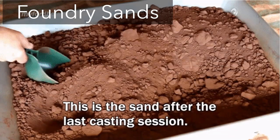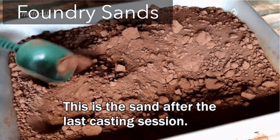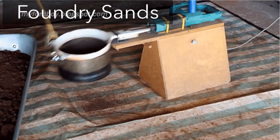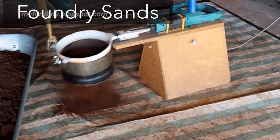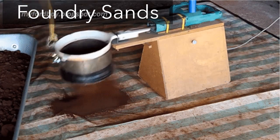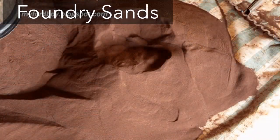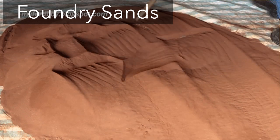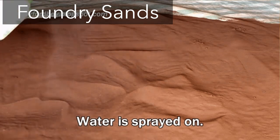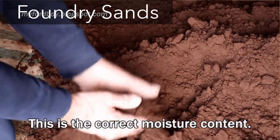Most sand casting operations use silica sand as a mold material. The sand is inexpensive and is suitable as a mold material because of its high temperature characteristics and high melting point. There are two general types of sand. We have the natural bonded, which is known as the bank sand, and the synthetic, which is known as the lake sand. Because the composition can be controlled more accurately, the synthetic sand is preferred by most of the foundries. And for proper functioning, the mold sand must be clean and new.